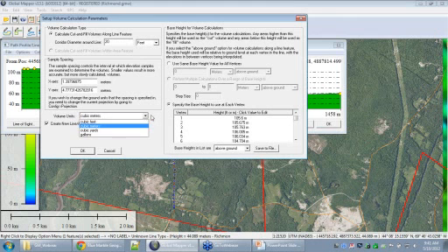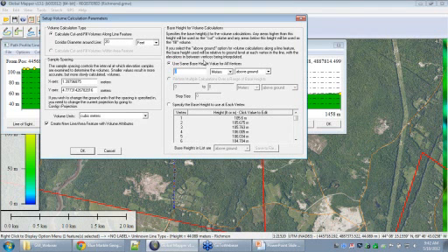So what we're going to be talking about in terms of units for dirt, we can select whatever volume we like there. We can optionally create a new line or area feature that has the output of this volume calculation attached to it. And what we need to do simply is select an elevation or a depth. So in this case, let's say, for example, we need to dig out that road bed 2 feet. So I'm going to say, let's dig that out